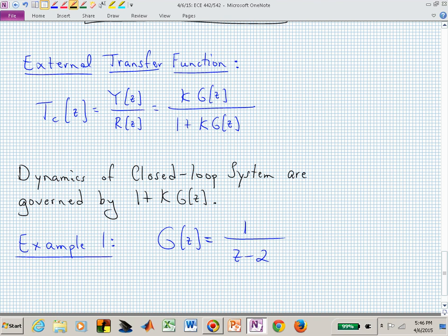That corresponds to a 5% overshoot. It's a nice trade-off between speed of response and overshoot. It's not a lot of overshoot, but it helps you get to where you're going quicker than, let's say, a zeta equal to 1. But if I haven't specified, pick zeta.